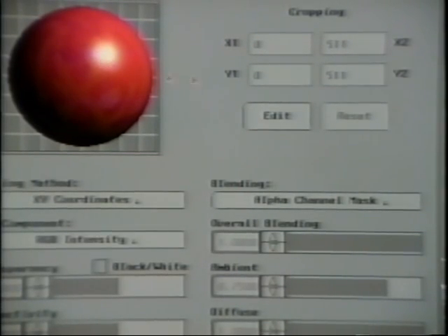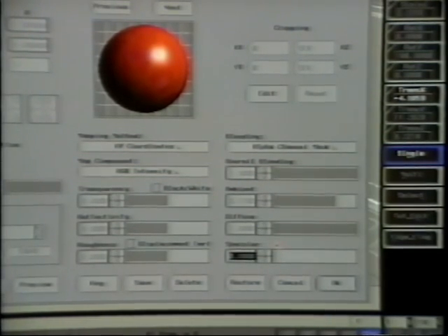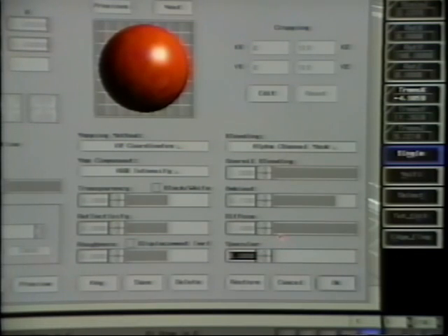When one of these three ambient, diffuse, and specular sliders is at 0, then the texture's influence over that attribute of the surface is turned off. So while the diffuse slider is at 0, the surface uses the diffuse color that was set in the material or in a previous texture. Once the slider is set to any non-zero value, then that color of the material is completely replaced by the color from this texture map, or could be blended according to the blending settings above. Once a slider is at a non-zero value, its value adjusts the brightness of that attribute of the texture, not the blending.